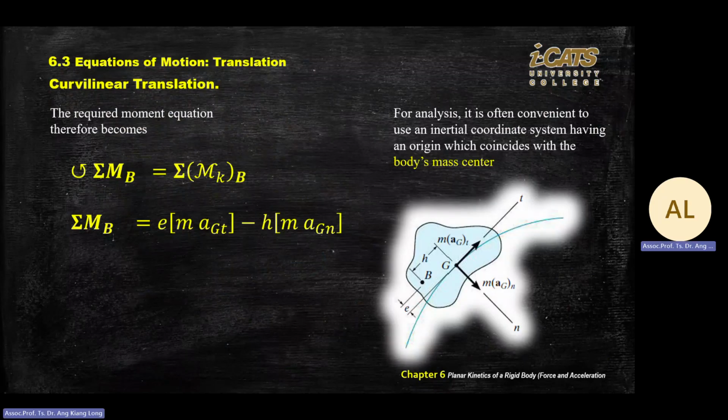How do you find the answer if you're given μs? Same, ΣF equals ma. Because with μs, your a is always 0, so actually you're finding an equilibrium equation. ΣF equals ma when it's static, still using ΣF equals ma, but your a is 0.